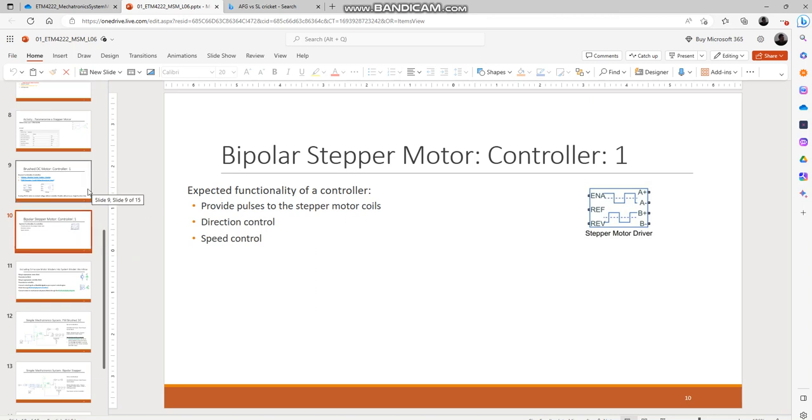And in a similar manner to the parameterization of motors, you'll be needing to parameterize the drivers and control H bridges and PWM signal sources as well. But mostly these will be the nominal voltages and any phase differences or duty cycles of the signaling sources. And these would depend on the application that you are choosing. So I won't be able to give any hard and fast guidelines on what to use.